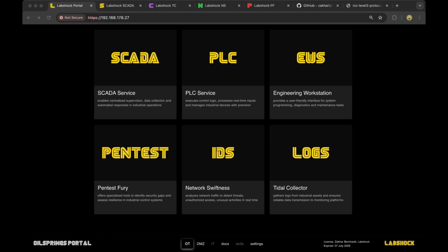What are common Modbus misconfigurations that increase the risk? A common misconfiguration is having open writable tags inside your PLC. If you have the possibility to write commands, it can be misused and abused by someone else. So if it's not necessary to have writing to outputs, you need to make it read-only.